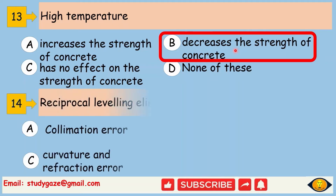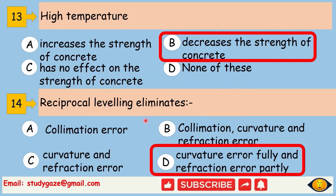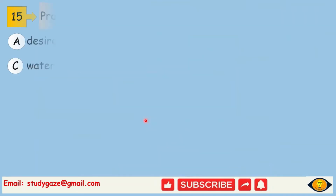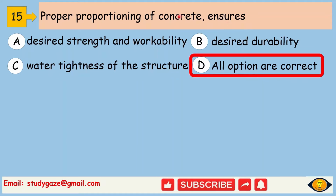Next, reciprocal leveling eliminates. So which type of error does reciprocal leveling eliminate? So the option is curvature error fully and refraction error partly. Next, proper proportioning of concrete ensures. Correct option is all options are correct. So proper proportioning of concrete ensures desired strength and workability, desired durability, and also water tightness of the structure. So all options are correct.